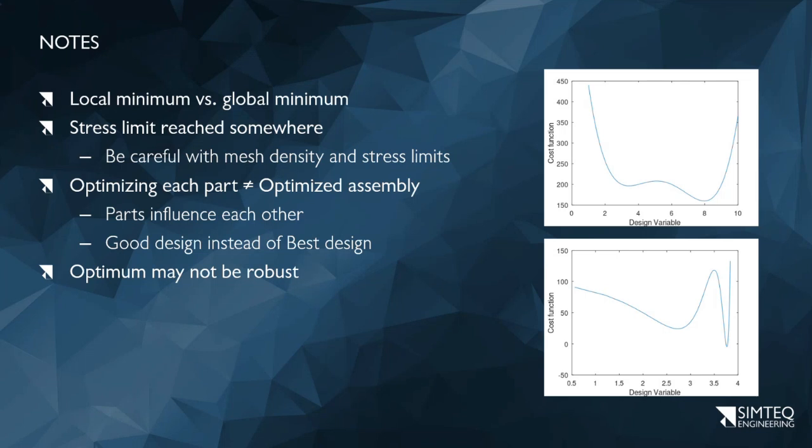In other words, is it robust? Does it allow me enough leeway that manufacturing tolerance will still give me a good answer? So it'll typically happen if I design for this optimum and I make 20 parts and I measure each of those, I'll see very similar behavior between all of them. If I do it for this, I'll see some great ones and some really bad ones.